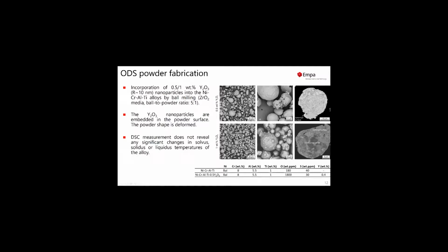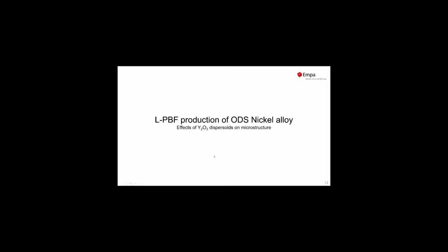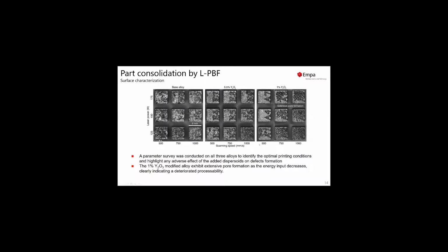So with these, we could start. The first part of our work was looking into the consolidation behavior of this ODS nickel alloy, and what effects the yttria particles have on the microstructure. We went for a very standard approach: we varied the volumetric energy density.